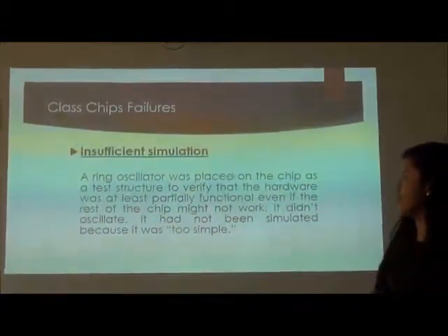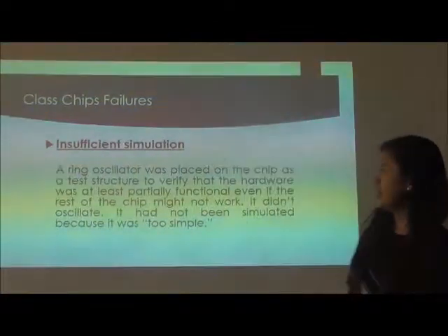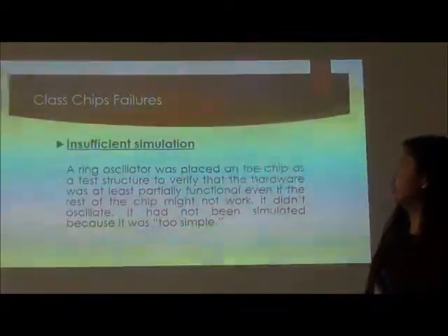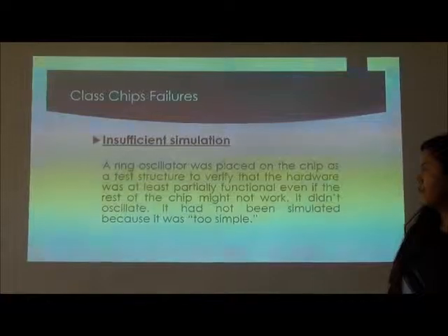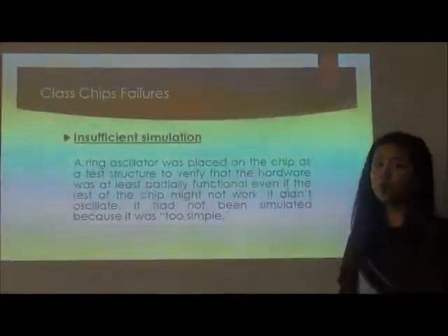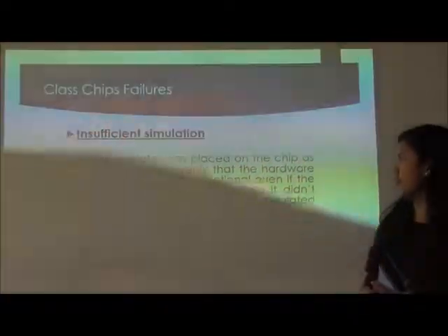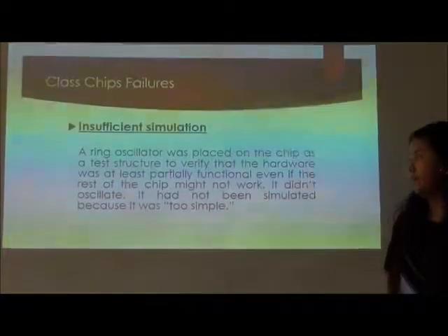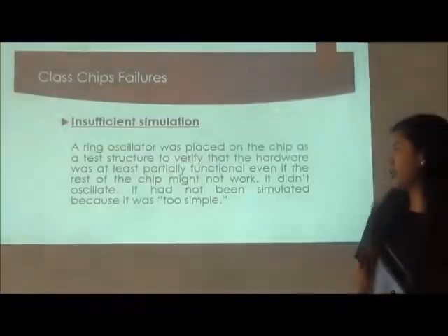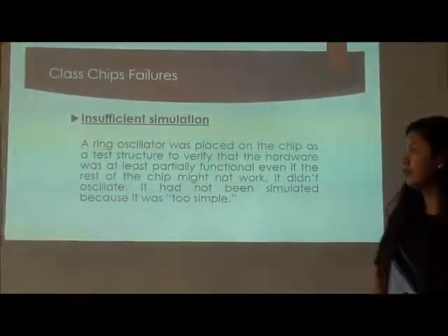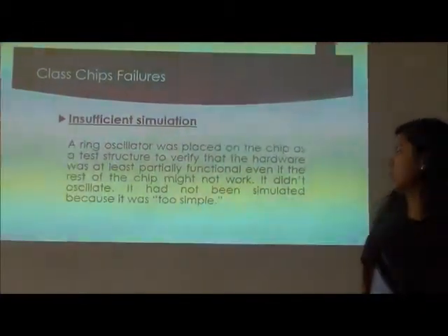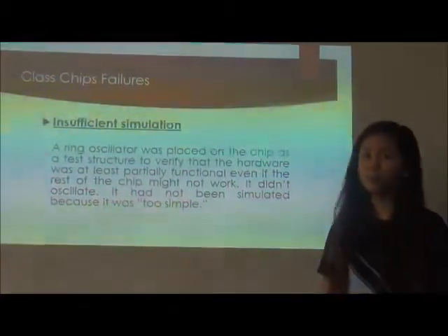Next is insufficient simulation. A ring oscillator was placed on the chip as a test structure to verify that the hardware was at least partially functional, even if the rest of the chip might not work. It didn't oscillate. It had not been simulated because it was too simple.